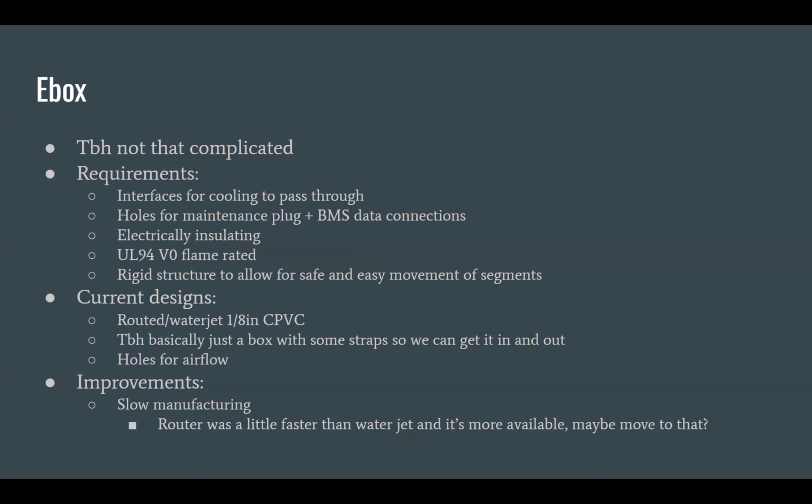Like I said, it needs to have holes so that the connectors can stick through the top. Same thing, it needs to be electrically insulating. Obviously, basically any form of plastic will have way more electrical insulation than you need. Technically, in the electrical systems form we need to submit, they do ask you to calculate what your voltage rating is, but any amount of plastic is going to always have a voltage rating of many hundreds of volts per millimeter.